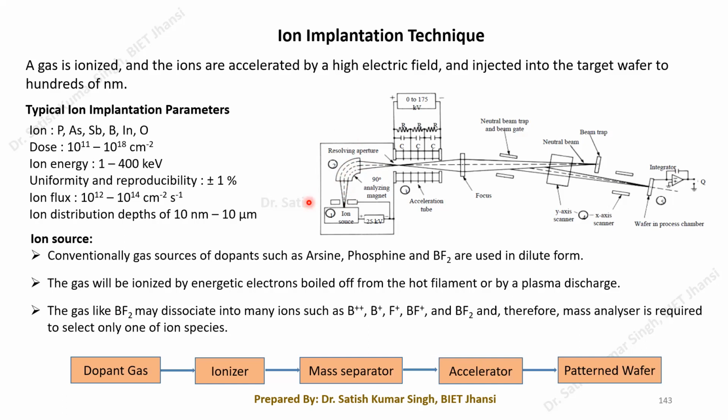Okay, magnetic field intensity can be controlled, and that way we can control particular ion beams, right? So this way only a certain ion beam will pass through this particular slit. All other beams cannot be selected; they should be filtered out. Only one particular beam should be selected, and then this selected beam will be accelerated further so that it gains sufficient energy for the doping purpose.